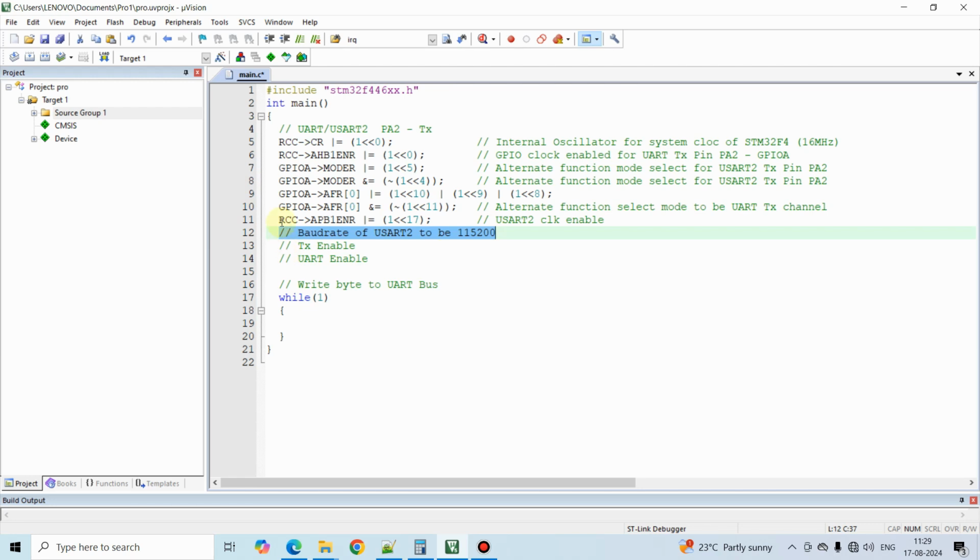This baud rate is an important feature that you want to note, because the device that is transferring the data in UART and also the device that is receiving the data in UART bus must always operate at a common baud rate.